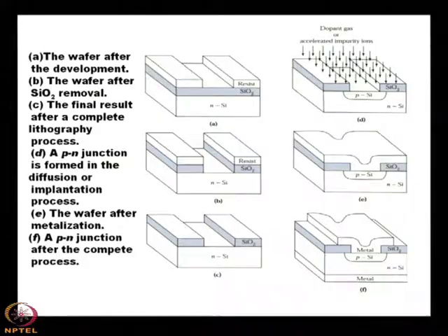Yes. Here you are doping, then is it pushing the dopant? No, it is not pushing, because you know that the mechanism of doping is that the dopant is taken inside the crystal lattice. So, there is no pushing or pulling in case of semiconductor doping. They are forming the bond, and where they go, we have discussed this earlier also, vacancy. If there is vacancy, there will be diffusion. If there is no vacancy, there will be no diffusion, but fortunately there will be sufficient vacancy in the crystal.